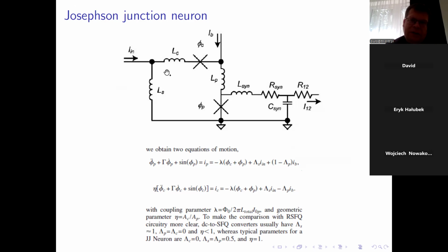basically you have here ideal superconductance that stands for those inductive elements. It's just part of a superconducting strip, and then this superconducting strip is interrupted by non-superconducting material that stands for the Josephson junction, that's a cross. And then you have also some resistor presence and capacitance presence. I think quite naturally, the capacitance is also associated with the Josephson junction existence, because simply saying there is insulation material in between that does represent capacitance to a great extent.